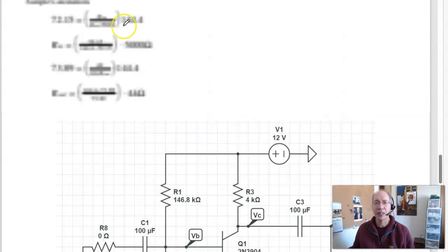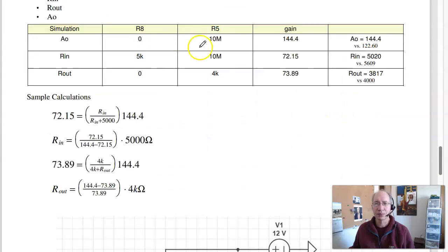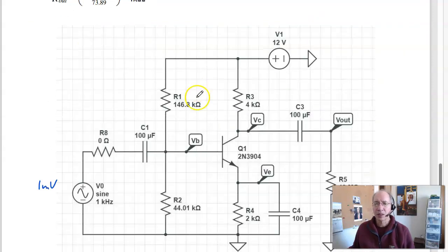In CircuitLab, I actually saw 144. So it gains a little bit higher than I expected. That's probably your N. So RF is NVT. Change N, I change the resistance, which changes the gain. Next, for Rn, define Rn, I'm going to change R8, make that bigger.